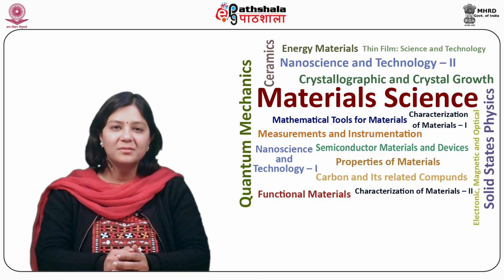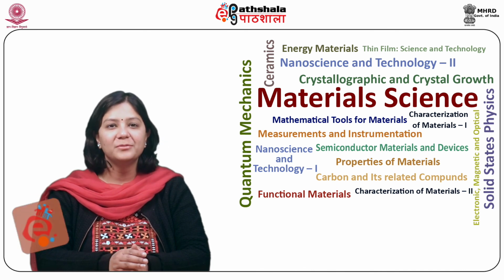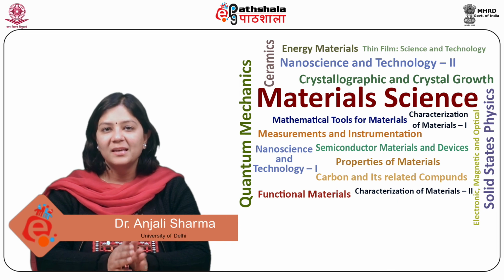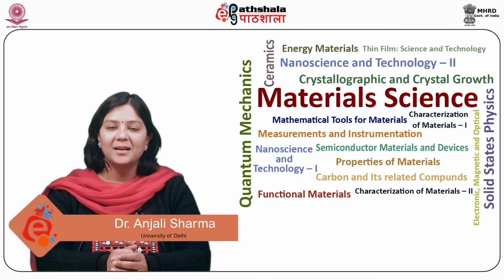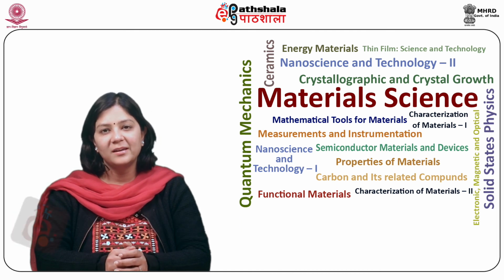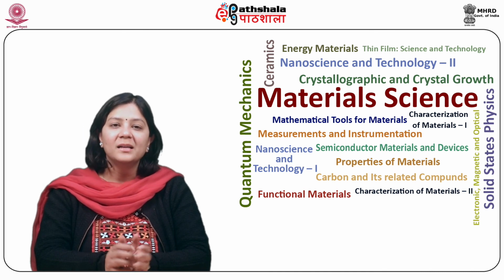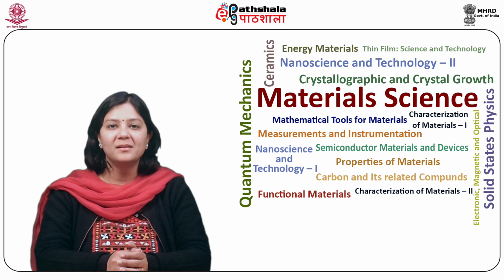We have understood the working principle of vapor phase epitaxy, the reactor components used in it, gas inlet and switching systems, gas exhaust and cleaning system. We also studied the environment, health and safety issues related to metal organic vapor phase epitaxy, and we have seen the quantum dot fabrication using metal organic vapor phase epitaxy.